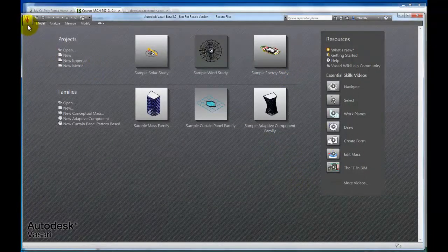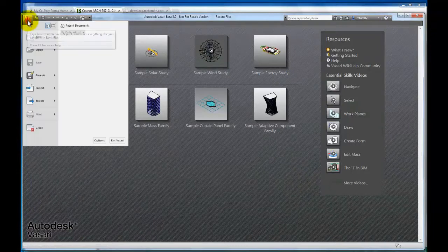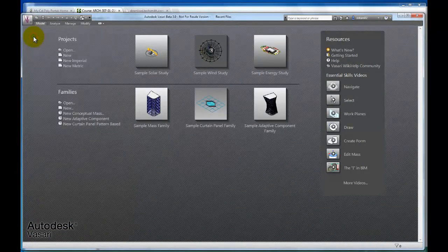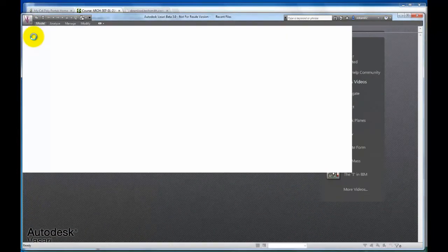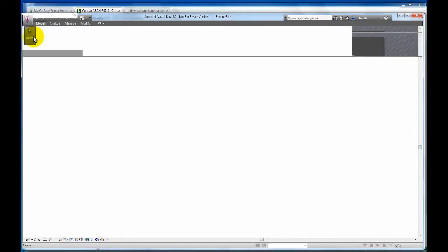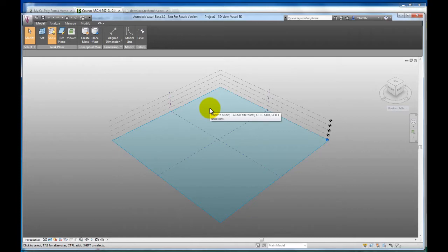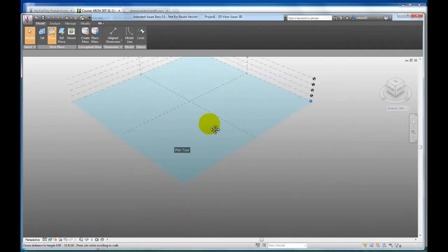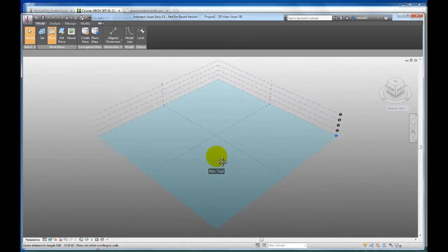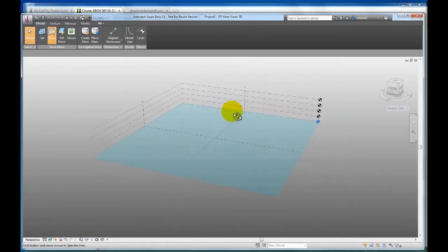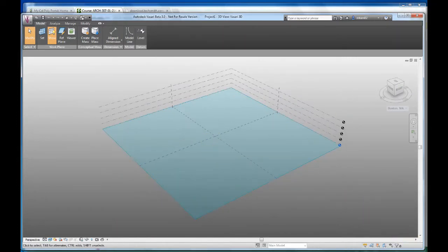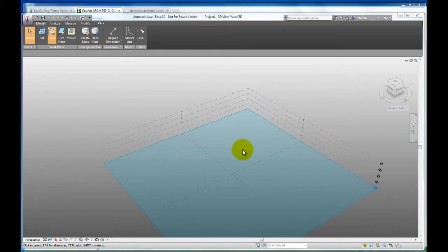And then next, once you have activated the license, go ahead and open up a new document. Now for those of you who have used Revit before, you're in luck. Being Autodesk, Vasari has the same operating tools, but if you haven't, well, you're also in luck because it's a good time to practice. Controls are pretty basic. Hold down your click wheel to pan and press shift while holding down the click wheel to rotate. So we're doing a pretty basic model today.